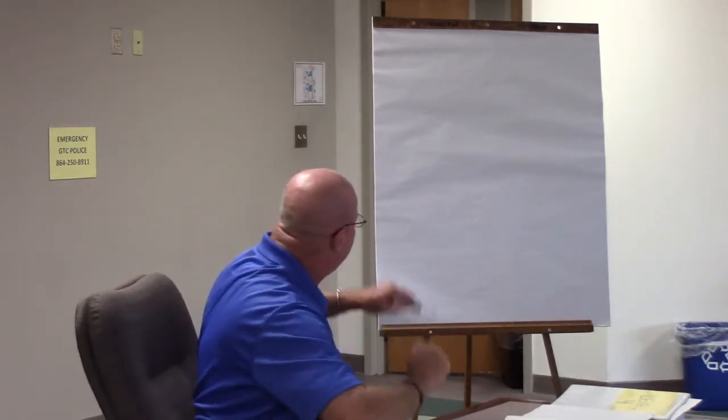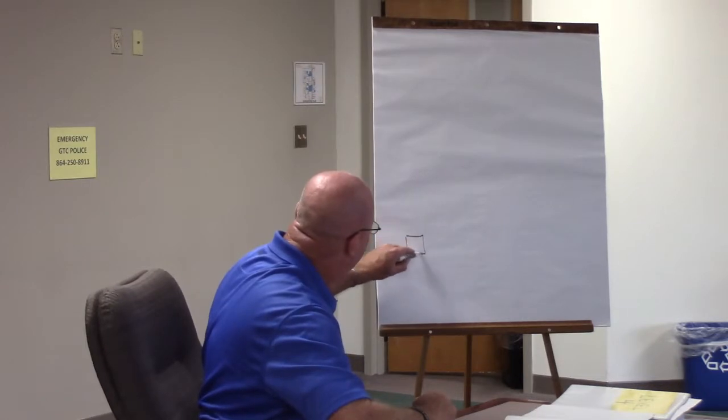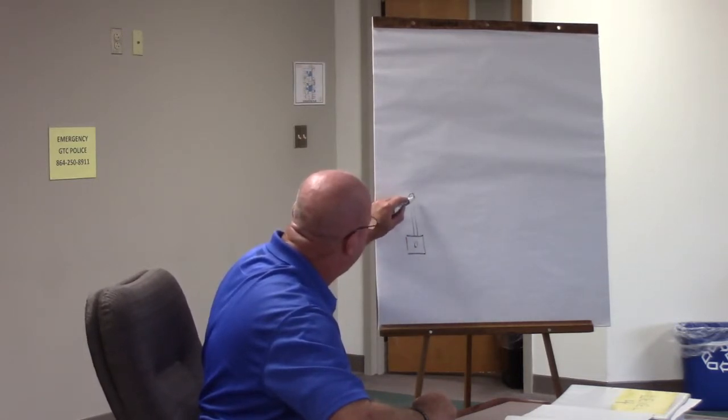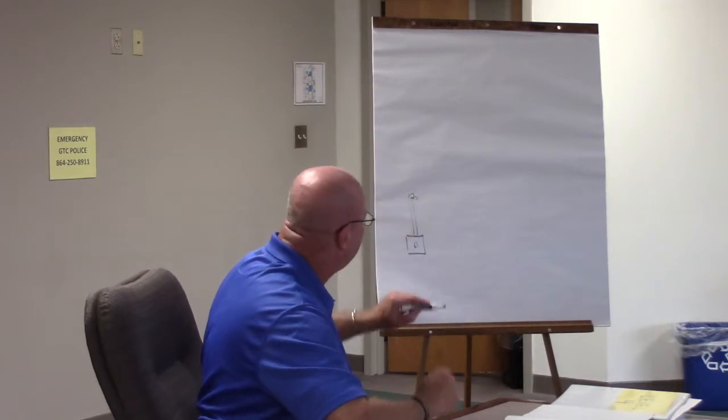Very good. We find that in our trade terms or definitions. Overhead, and that makes sense. Overhead service conductor. We talked about it last week. We drew it on the board. Overhead conductor between the utility service supply system and the service point is when we have our meter, and then overhead with the weatherhead, and then our wire. That's our service drop. Okay. All right. Number 3.